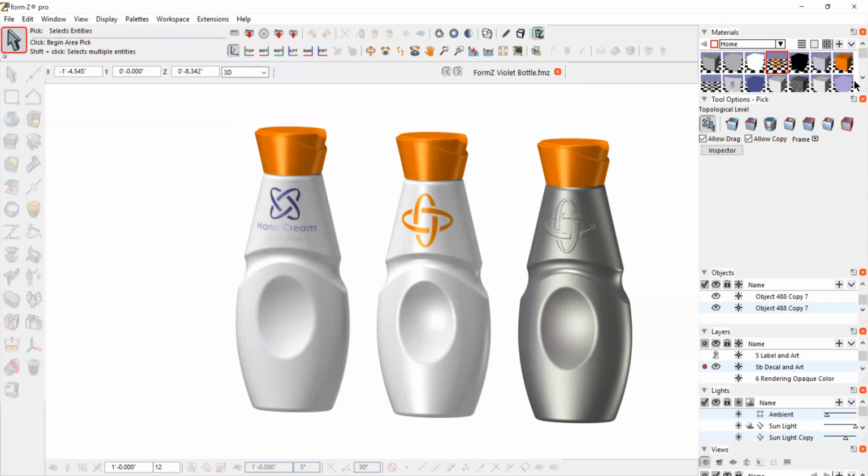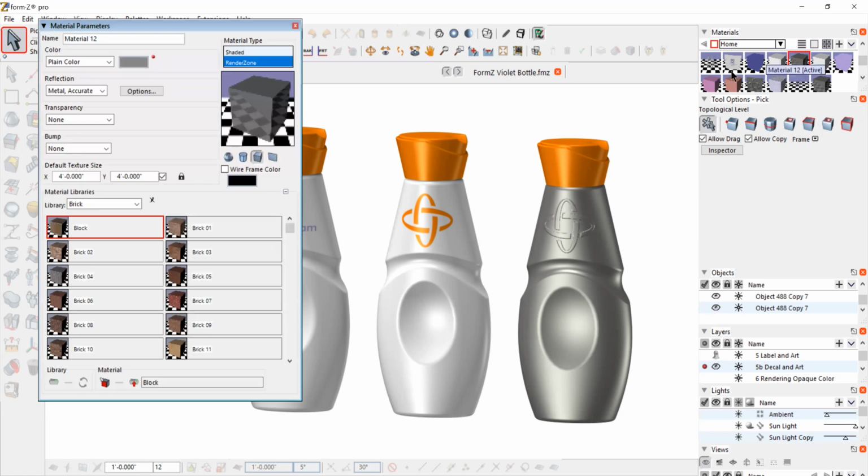This third one was a little bit different. What I want here is I want our decal to look like it's creating an in mold part in here, where it can be set in or protruding, concave or protruding out. So what we have to do is I set up the color of this. I added some details to make the coloring on this a little more interesting. And when we do a decal like this to show an in mold part, we need to set up the color first, because I want to make the decal map the exact same color.